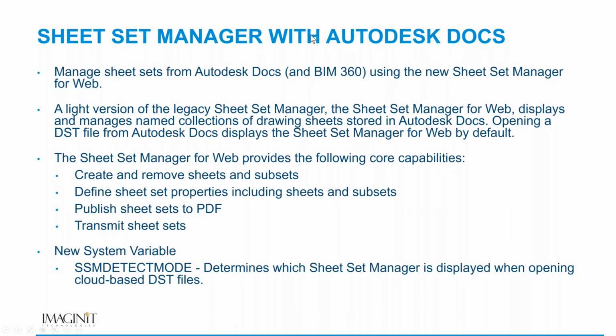So the sheet set manager with Autodesk Docs. You can now manage sheet sets from within Autodesk Docs and BIM 360 using the new sheet set manager for web. Now, it is a lighter version of the legacy sheet set manager and displays and manages named collections of drawing sheets stored in Autodesk Docs. Opening a DST from Autodesk Docs displays the sheet set manager for web by default.